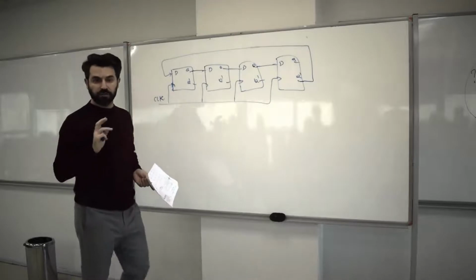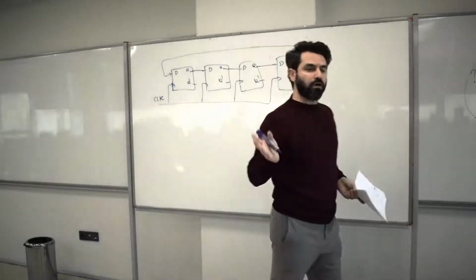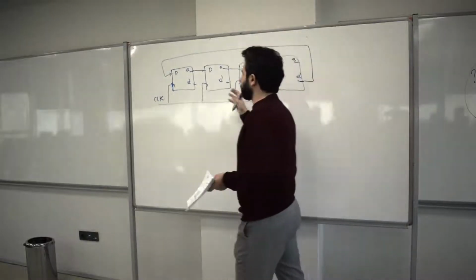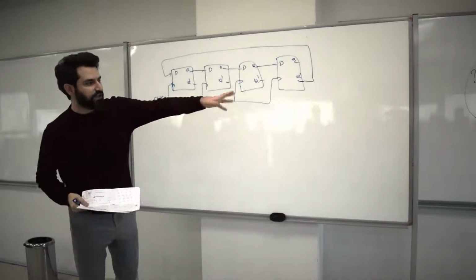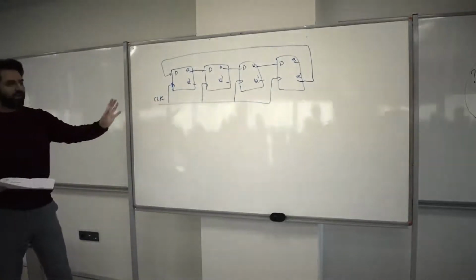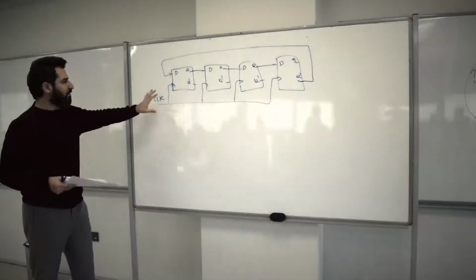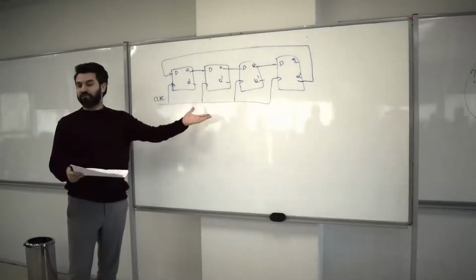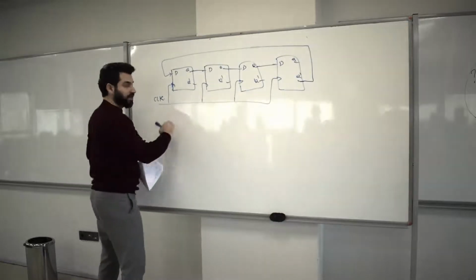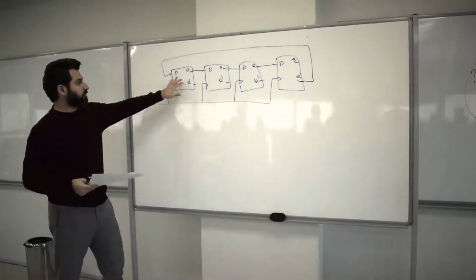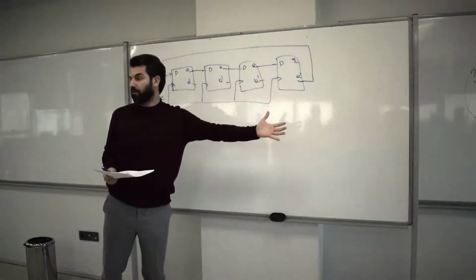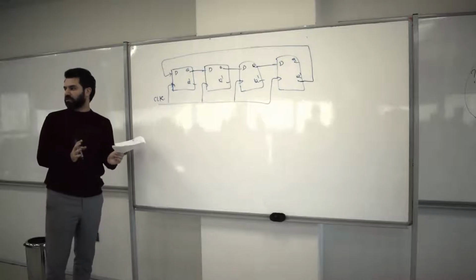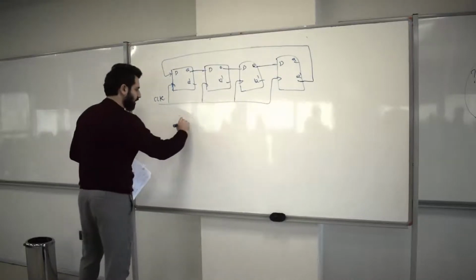That's the first workaround to refrain from starting with this weird initialization, 1, 0, 0, 0. Instead of 1, 0, 0, 0, now you can use 0, 0, 0, 0, which is the default initialization given to the flip-flops. In other words, you can start without doing any initialization because those flip-flops are usually initialized to 0 by default. They've got their own small circuit that establishes those initializations. So you start from 0, 0, 0, 0.